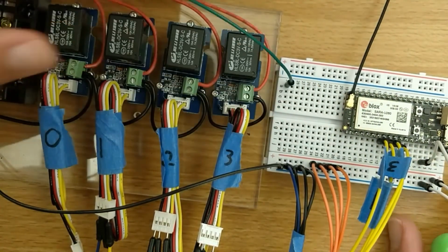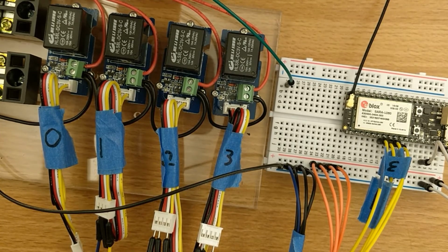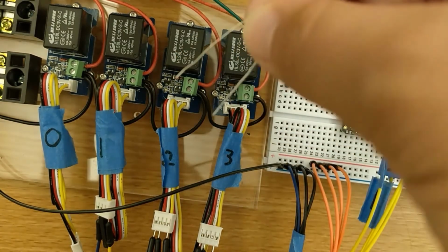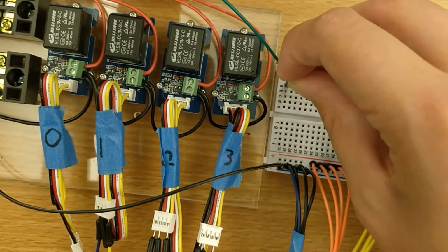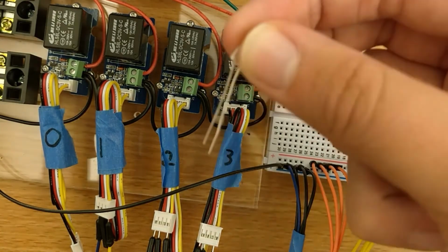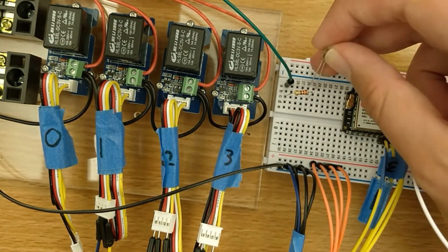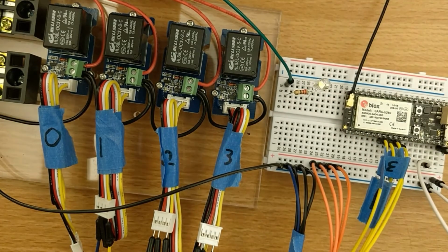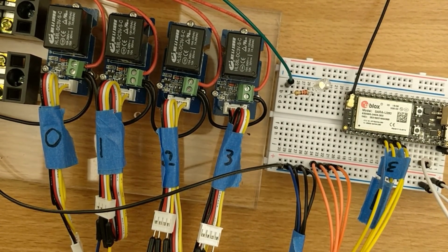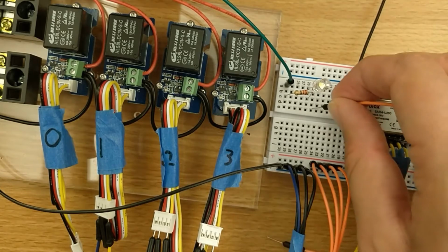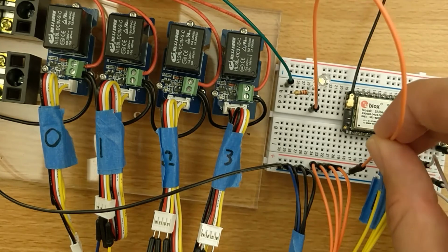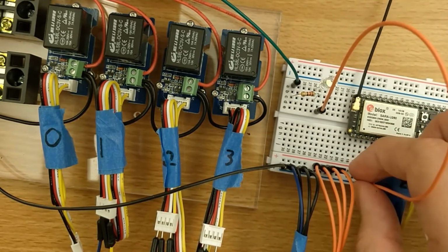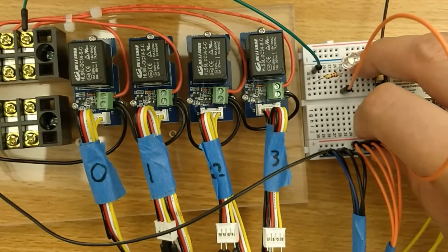I'm going to plug it in an empty row, and then I will take my resistor that I used earlier with my LED and plug it in, just for convenience, with the ends in different rows. And then I'll take my LED and stick the long end in one row and the short end in the same row as the resistor. And finally, I'm going to take this orange wire and plug it in the same row as my LED, and then also in this column with the high voltage. And it should be ready to go.